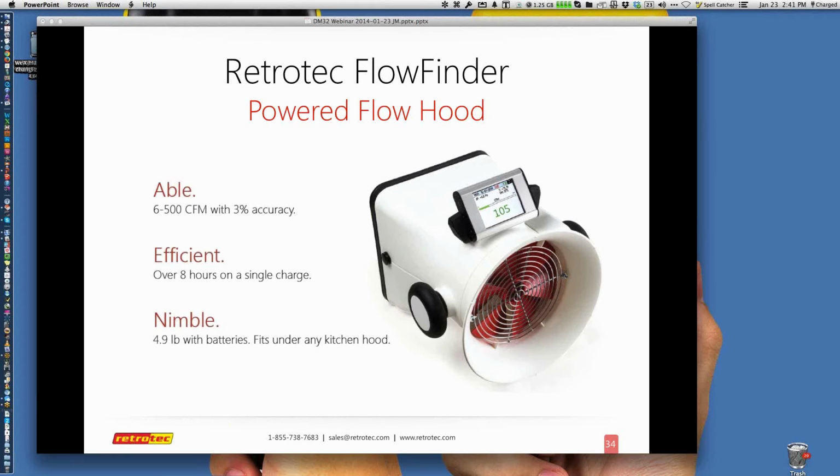Well, with this device, we take the rectangular hood that you see and we push it up to the exhaust fan or whatever we want to measure. And you can't see it in this picture, but there's a little tiny red button beside one of the knobs. You simply press the button, and the red fan that you see there starts spinning, and it's the part of the device that will do the zero pressure balance.